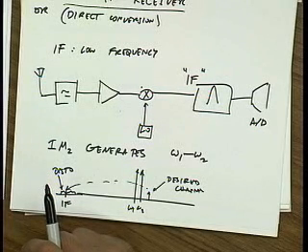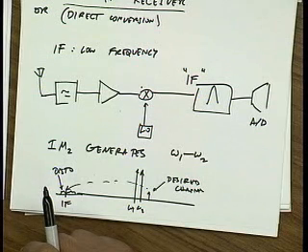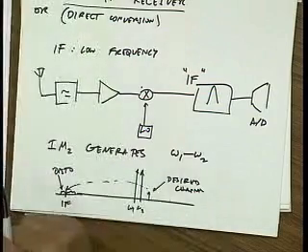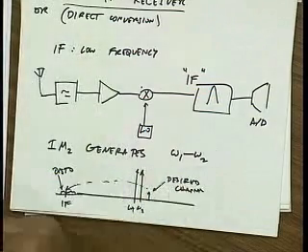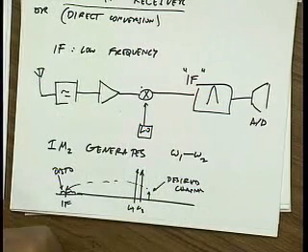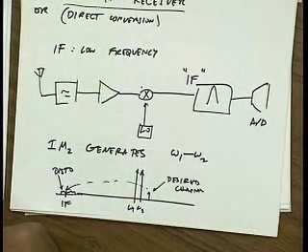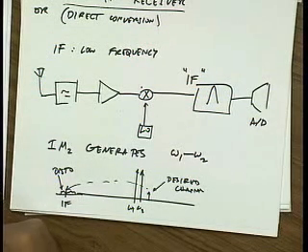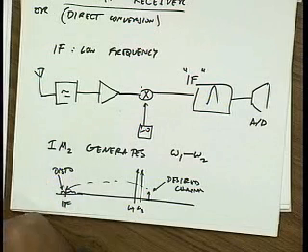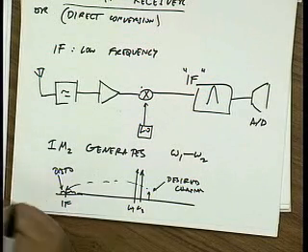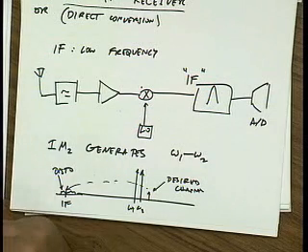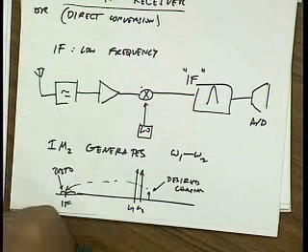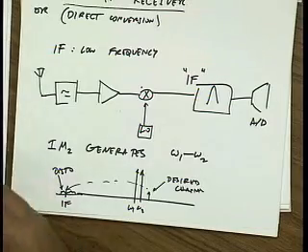Because if we have two tones very close to each other, and we have the third harmonic, then... Okay, you're getting too complicated. Forget about third harmonic. So let's just say, for this system, would that be an issue? If I had differential architecture, would that solve the problem? No? Yes? Well, remember, you can never build a perfectly differential signal path. There's always going to be mismatch. So there will always be residual second order due to matching constraints. You know, in integrated circuits, you build two transistors, you make them the same size, they come out different, right? Because they're so small, there's going to be lots of variation due to doping, due to lithography, and so on.